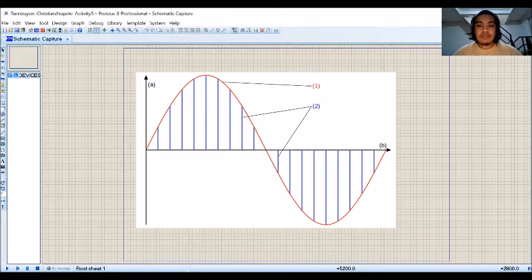Now, let us move back again to PAM or pulse amplitude modulation. It is a technique in which the amplitude of each pulse is controlled by an instantaneous amplitude of the modulation signal. It is a modulation system in which the signal is sampled at regular intervals and each sample is made proportional to the amplitude of the signal at the instant of sampling. This technique transmits the data by encoding the amplitude of a series of digital pulses.